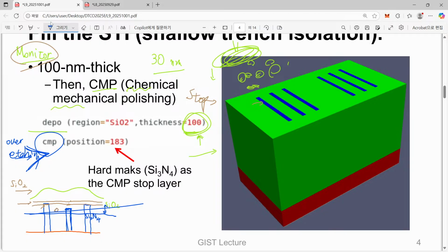However, nowadays, if we look at the process integration in our state-of-the-art devices, the use of CMP is widespread. In many cases, we always try to perform CMP to make a planarization, because once we make this planarization, we have the same starting point, and it is easy to control the final profile.